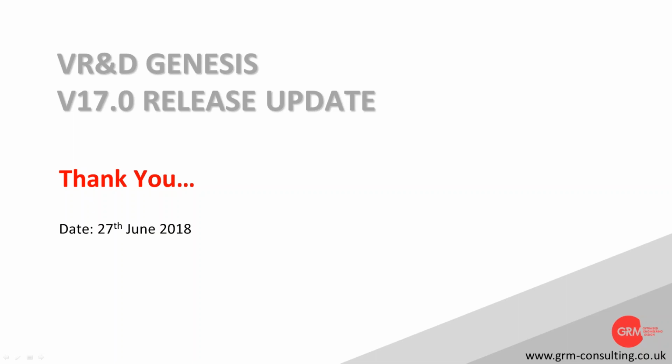Next question, do you recommend to use a stiffness constraint as well as stress? Not necessarily. In the case of this new VM index, it's really quite capable of just setting a stress target and hitting go, and that will minimize your mass fraction. It works quite well, and I think because of its almost consideration of the strain energy, it is fundamentally working on a stiff structure at the same time as monitoring your stresses.